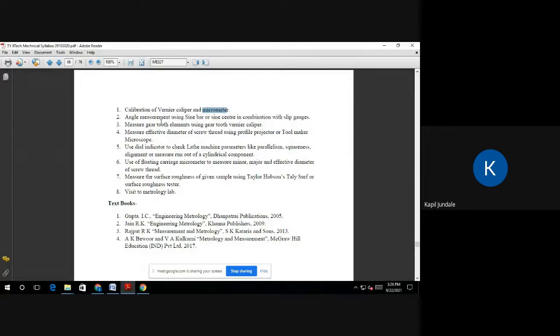Okay, now similarly, if we go for our steel rule, we can measure. Can you tell me the minimum distance we can measure with the steel rule? With the help of a steel rule, how much minimum can we measure? Can anyone? Or on our scale, correct, we can measure 1 mm. And if I use the vernier caliper, the minimum distance, or what we call the least count, what is the least count of the vernier caliper? Tell me.